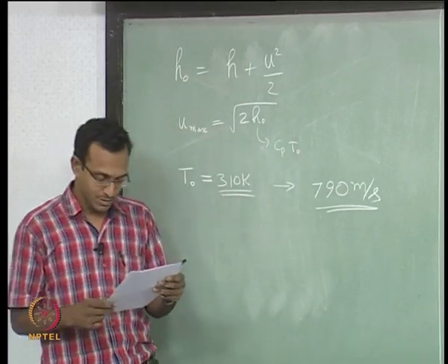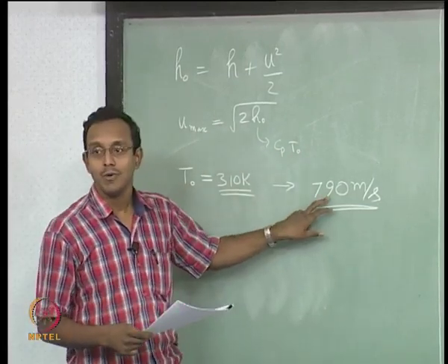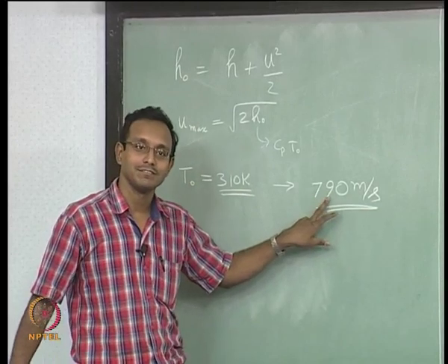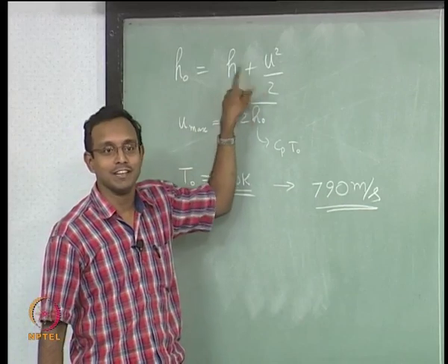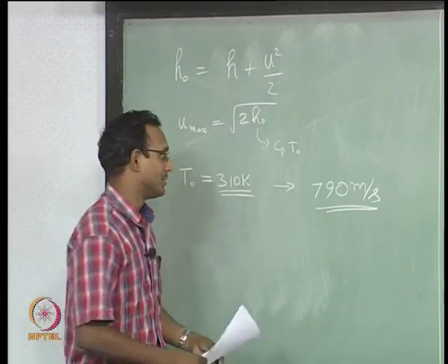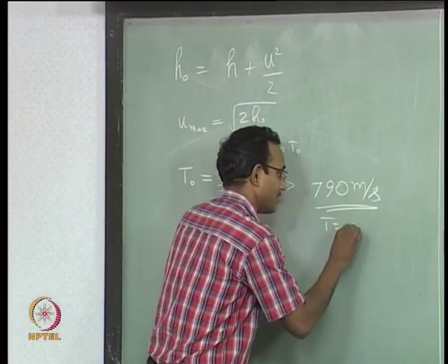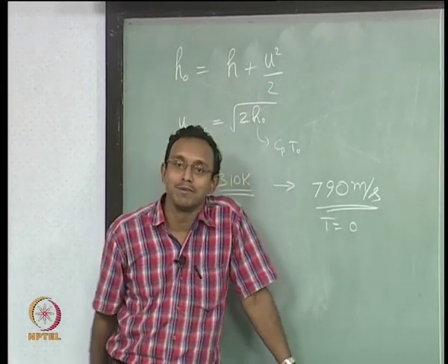When this happens, what is the temperature of the gas? It should be exactly 0, because I am saying h is 0, all the energy is inside kinetic energy only. So this will go to a point where T equals 0. If T equals 0, what is my Mach number?